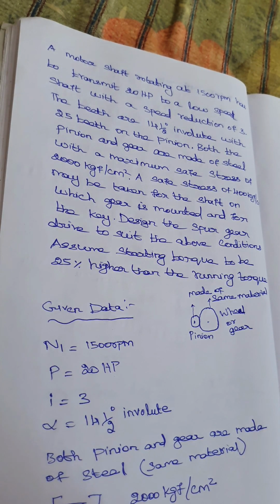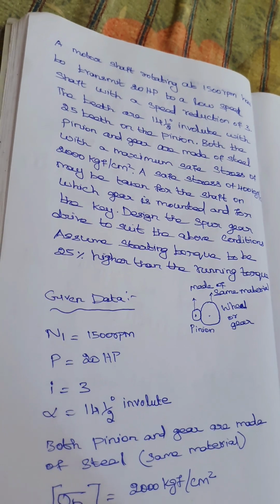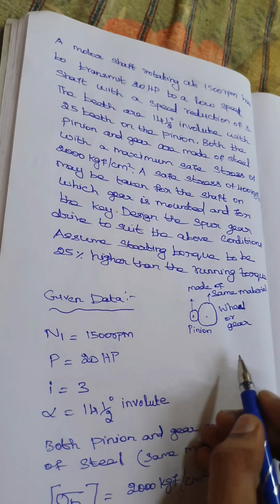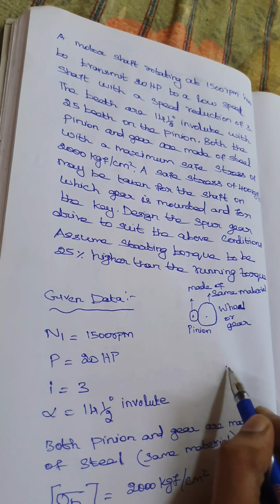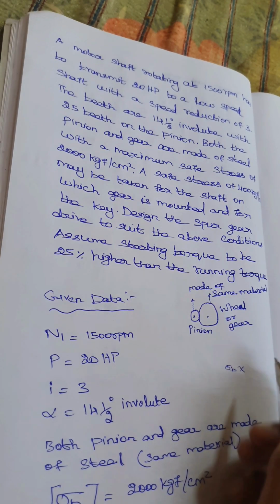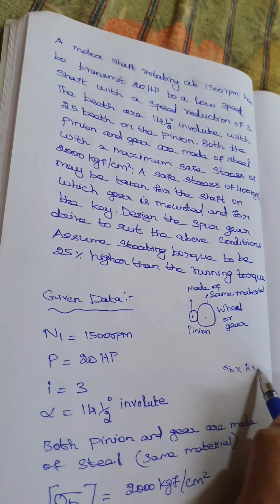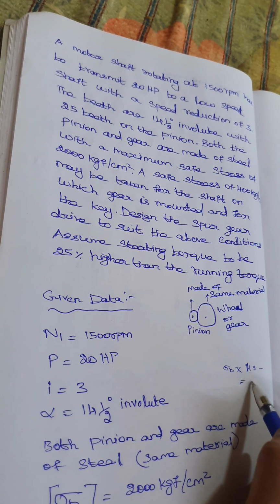If a value is given inside the bracket, then it is considered a design value. If the bracket is not given, then that value is considered a calculated value. The difference is that if the calculated value is multiplied with any factor, for example ks or kd, then that final value is considered the design value.